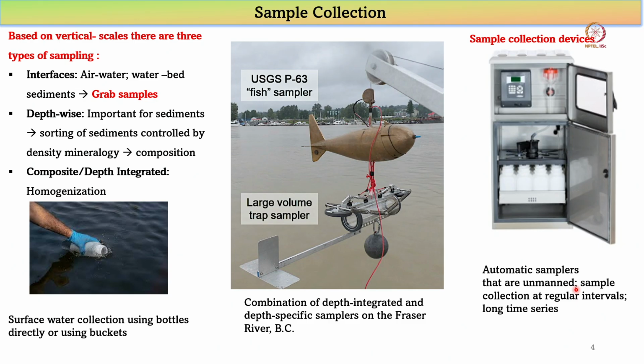So if the water is turbulent, just like in rivers, I would not say lakes, but certain places wherever there is turbulence, you can take a one-time sampling from the surface water, and it can give you a representative sample of the dissolved geochemical data.